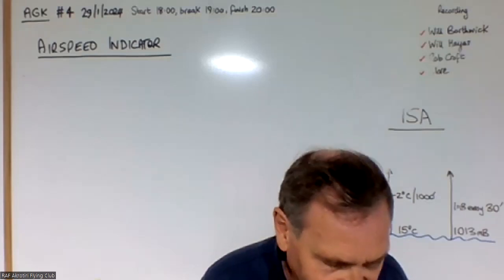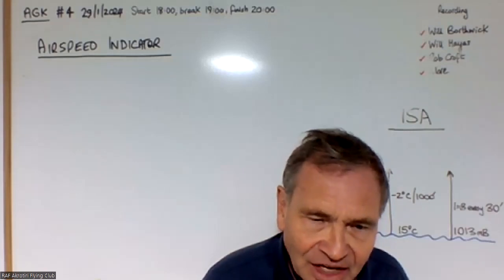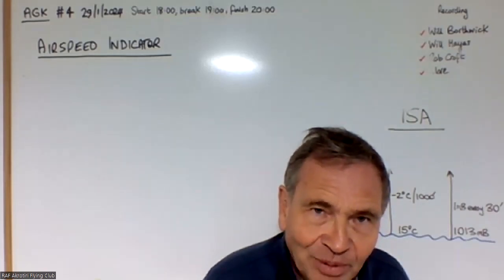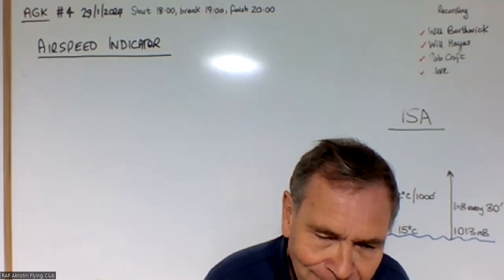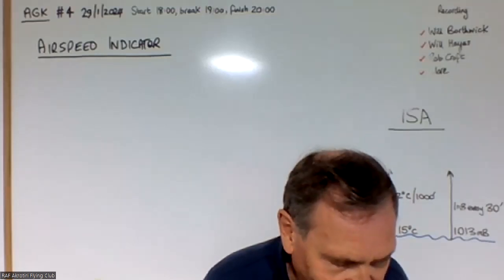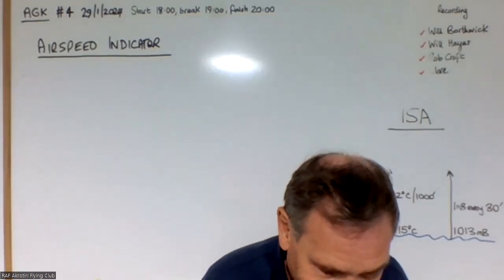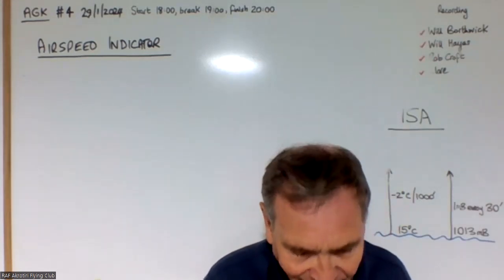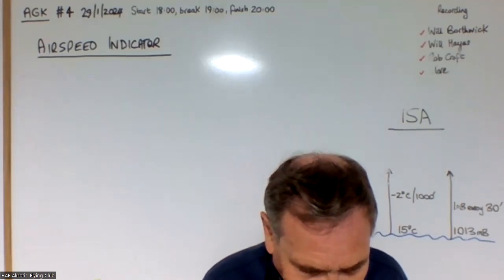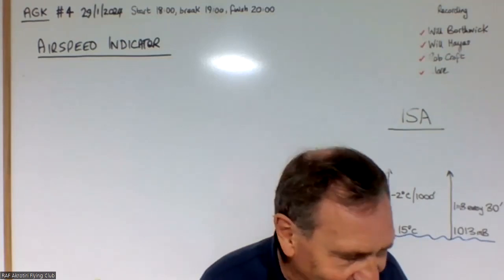Now, what's going to happen if I start descending? What do you reckon, Rob? Rob, if I start descending. The static pressure value should be increasing as you descend. Therefore, you'll start to get an inaccurate reading because the ram pressure hasn't deducted the increasing static pressure. Therefore, your dynamic will be incorrect. Will it be reading too high? Absolutely. High, you're dead correct.